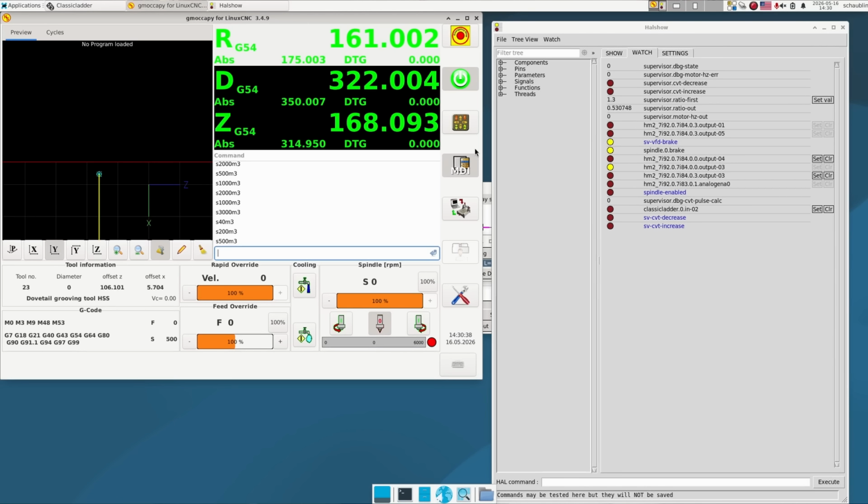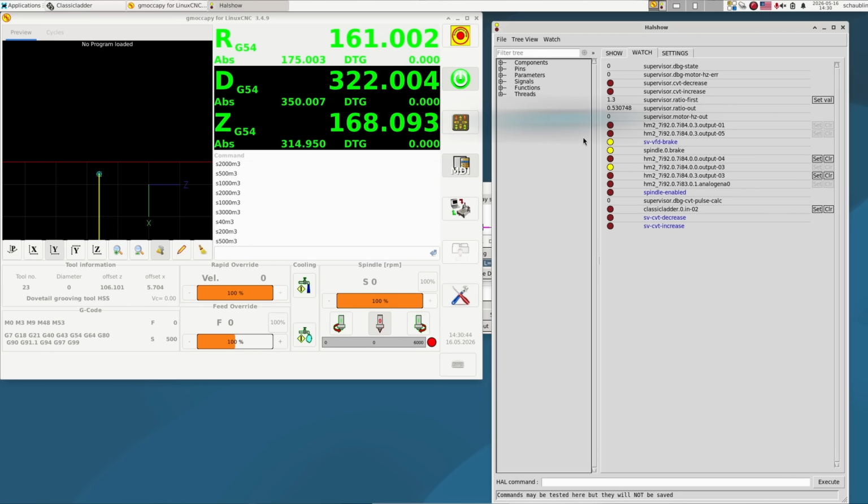After another week of mucking around with that, this is what it looks like. Regardless which speed I start at, it always starts at 10 Hertz up here. After about a second, it will have calculated the gear ratio. And based on that, it'll do a logic check. Am I on high range or low range? And is that correct for the commanded speed? The cutoff being 400 RPM. If it's got the wrong gear, it'll fault out. But otherwise it'll then start the spindle and try and accelerate with the VFD up to the target speed. And once it gets to that speed or gets to the maximum frequency of 70, it'll then look at adjusting the CVT to try and bring the motor RPM to 50 Hertz. Let's have a look.